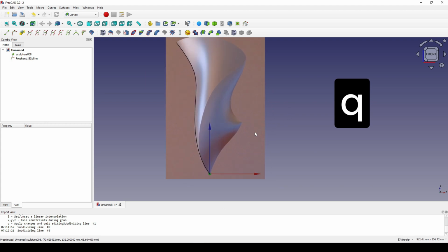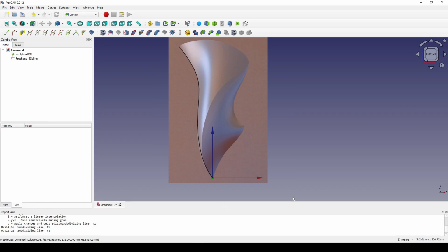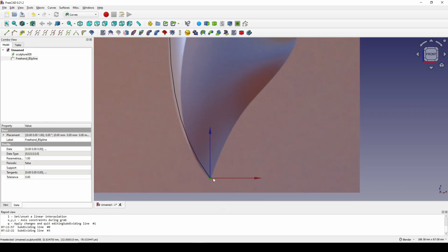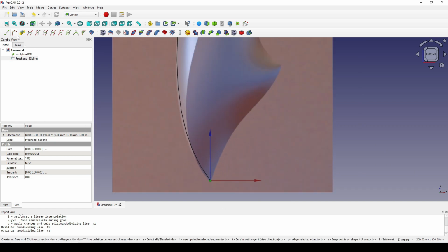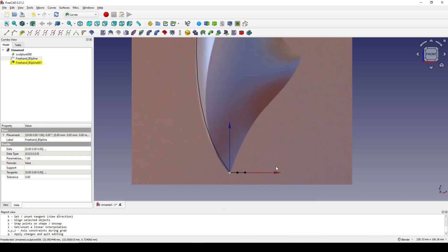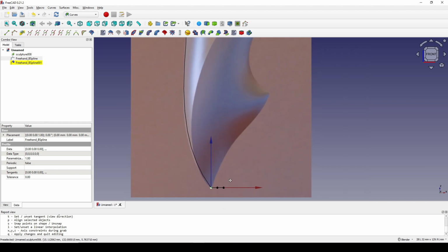All right. Now I want to create this curve over here. But you can see this curve is connected with this curve on the left. So before I create the Freehand Bspline, I zoom close here and I click on this point to select it. And I create another Freehand Bspline. Click on this one, and the new Freehand Bspline with this point connects with this line.